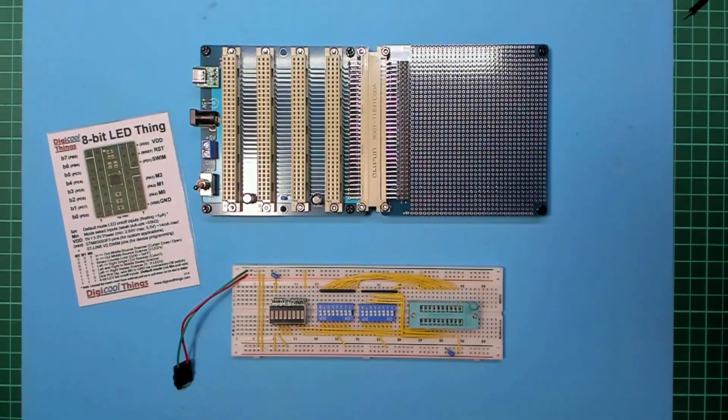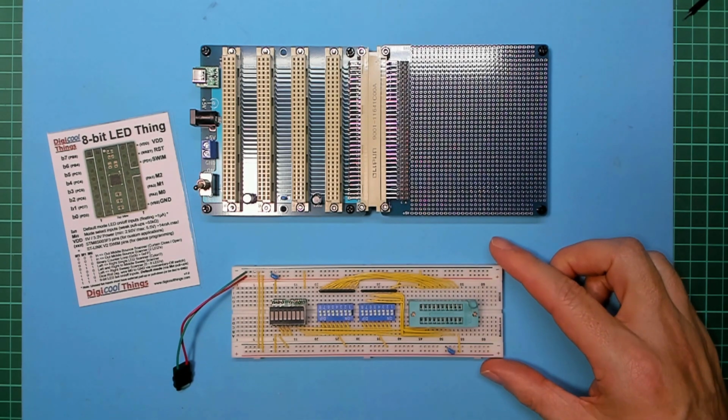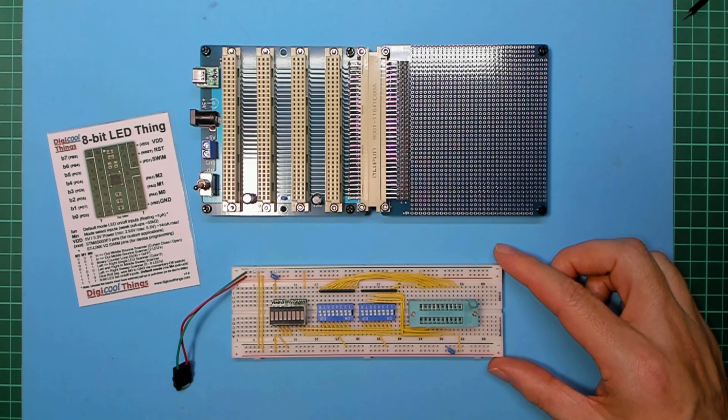And here is my breadboard creation. I have fitted a 20-pin zero insertion force socket for the easiest swapping of PLD chips. I then have 2 8-way DIL switches to allow switching all of our 15 assigned inputs, 1 switch unused. These simply are pulled high when off via a couple of 10K single inline resistor networks and switched to ground when on, to allow for manually pulling each possible input high or low.